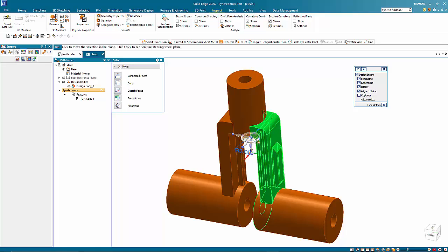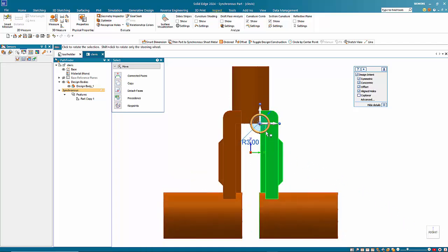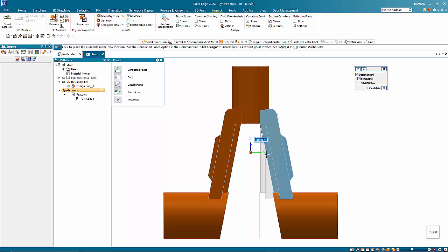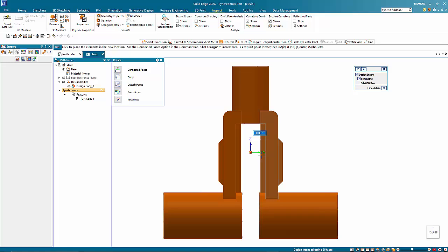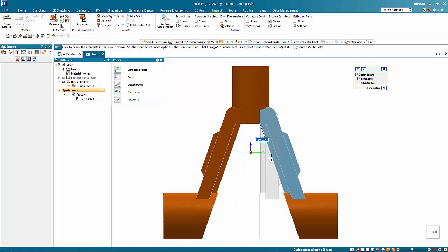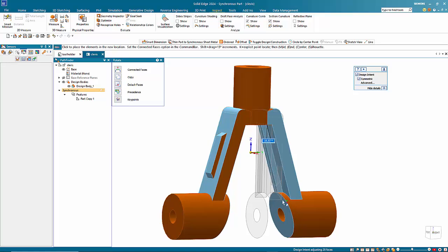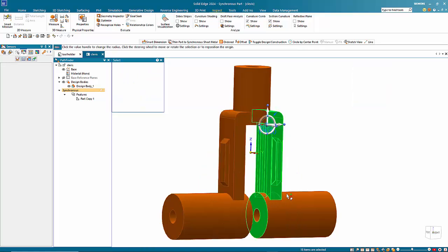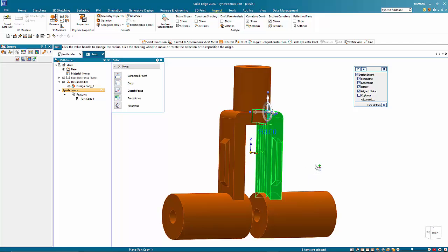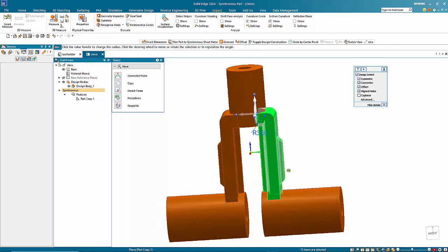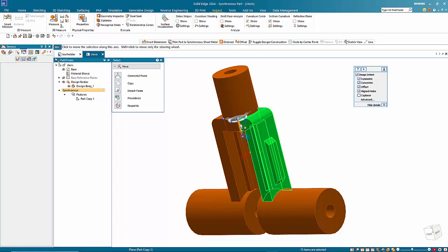So if I hold the shift key down and click on the torus just a couple of times to get the orientation right, you'll see that what we get is the ability to add some flange in here. So I've still got that internal face, so I'll keep that as is. If I want to, I could just turn that off. I hit escape and select that face with the control key. That turns it off. I need to rotate this around again.